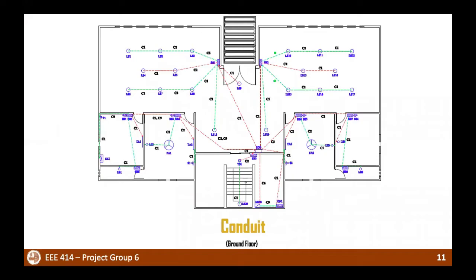This is the conduit diagram. The main distribution board is near the staircase, which is connected to the generator and a single sub-distribution board that runs the entire floor. 5 circuits in total are connected to the sub-distribution board, with a total of 9 switchboards. Some of the switchboards and loads are connected through the same conduit, and the conduit sizes are determined by the diameter of wires that will be inside. For example, in the parking space, C3 is needed for the 3 lights LS1, LS2, and LS3. After LS3, C2 is needed, and finally, C1 has been used to connect to LS1. For the 15 ampere socket in the kitchen, a larger conduit size, C9, is required.